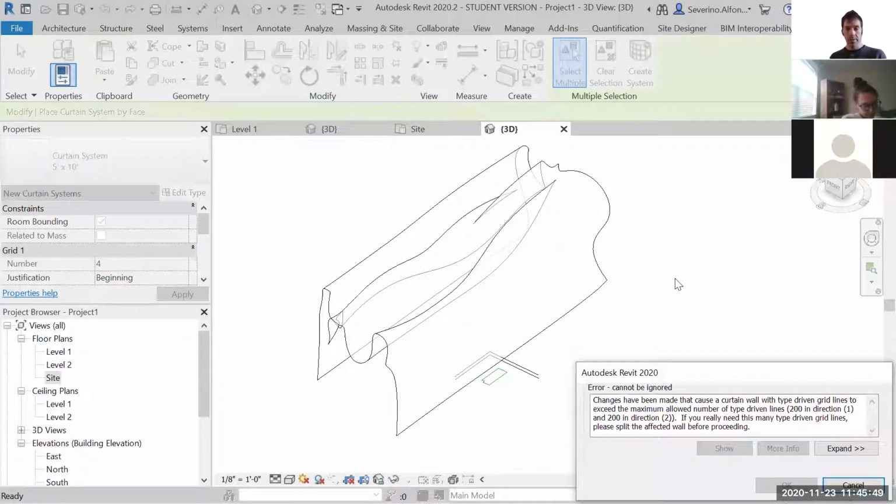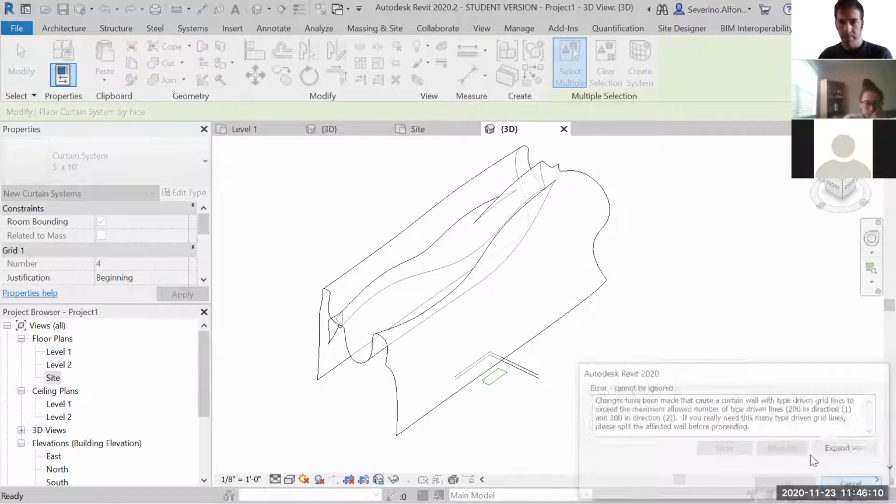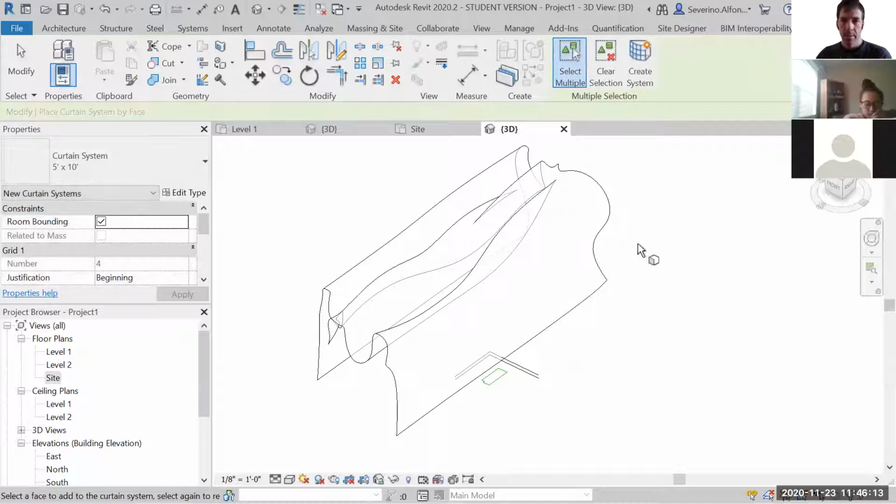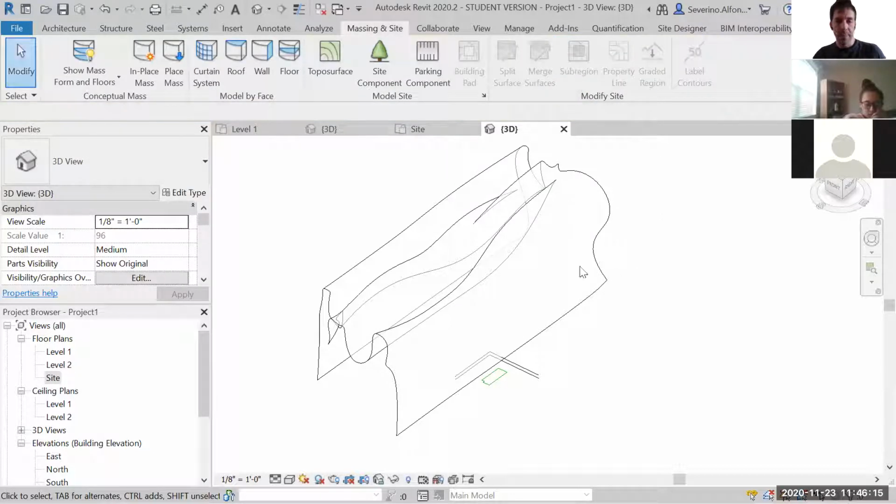And I can send you another video tutorial, but those are the steps. The step is always to take the line drawing to Rhino, model in Rhino the thing that you want to do, and bring it into Revit as an SAT conceptual mass, and that's the way you convert it through the massing inside options. I could have done a much easier or more relaxed surface. Let me actually stop this one.